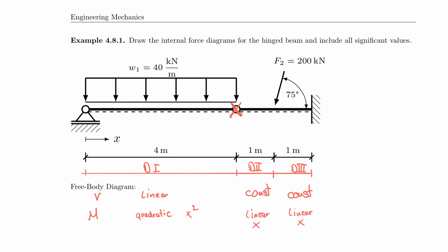So now it's just a matter of solving the problem, and we learned already that we can break this down into the two subsystems, the cantilever on the right side and the simply supported beam on the left side. Therefore all we have to do now is find the support reaction and use this to solve our problem.